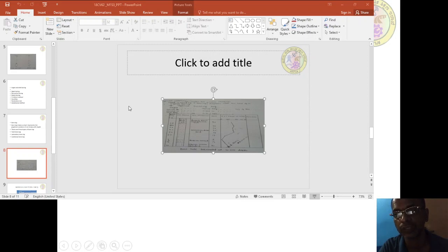Now if you see here, at 0 meter filled-up soil is there, and they found reddish brown soil, and SPT was 30. SPT means the number of blows required for 30 centimeter penetration of a split tube with 30.8 mm internal diameter, 50.4 mm external diameter, and a cutting edge of 60 centimeter length. After 15 centimeter of seating drive, using a 65 kg hammer with 75 centimeter free fall, the blows for the next 30 centimeter is called the N value. That is also called SPT. So for the first 0 to 1.5 meter depth, the SPT value was 30.